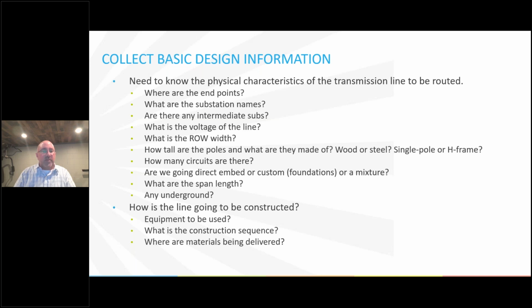What is the right-of-way width? How tall are the poles and what are they made of? Wood or steel, single pole or H-frame? How many circuits are there? Are we going to direct embed or custom or a mixture? What are the span lengths and is there any underground?